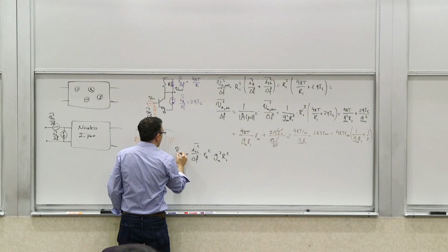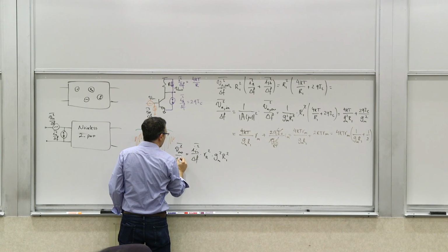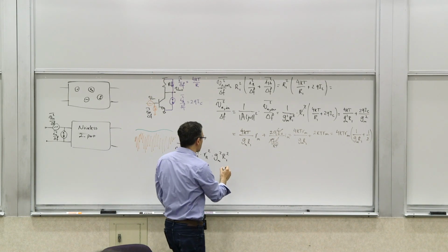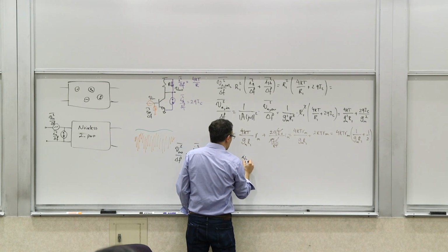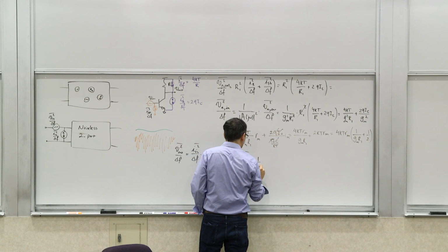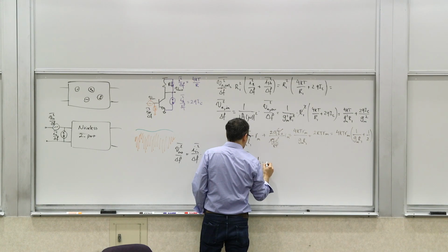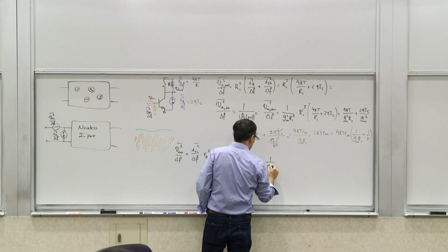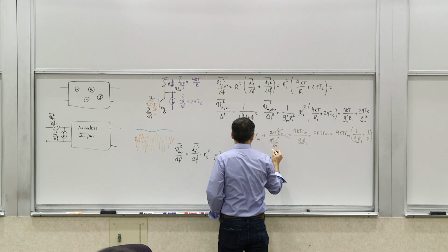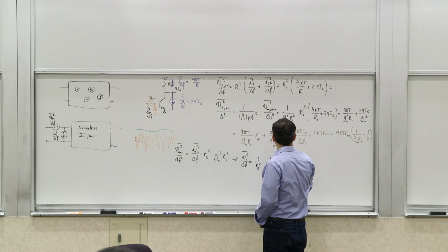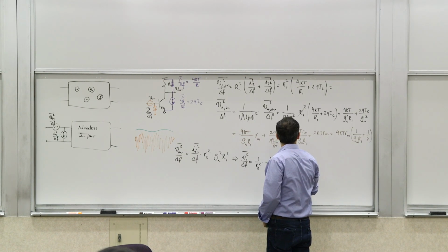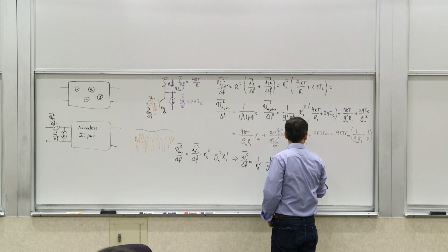So this is V out squared over delta F. Now we know what V out squared over delta F is, so from this we can calculate what I in has to be. I in squared over delta F has to be 1 over R pi squared times 1 over Gm squared R1 squared times V out, which is R1 squared, 4kT over R1 plus 2QIC.